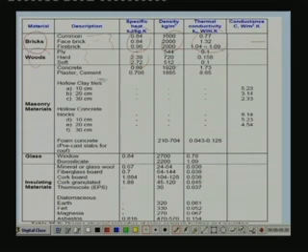When it comes to hollow clay tiles or hollow concrete blocks, the thermal conductivity values are not given, because here the heat transfer, as I have just discussed, is by multimode: convection, conduction and radiation. So for these materials the conductance values are given. These values are generally obtained from experimental measurements. For example, for hollow concrete block of 10 centimeter thickness, this is the conductance value. For 20 centimeter thick, this is the conductance value. For 30 centimeter, that is the conductance value. Similarly for foam concrete, this is the density value and this is the thermal conductivity value. Similarly for glass and for insulating material.